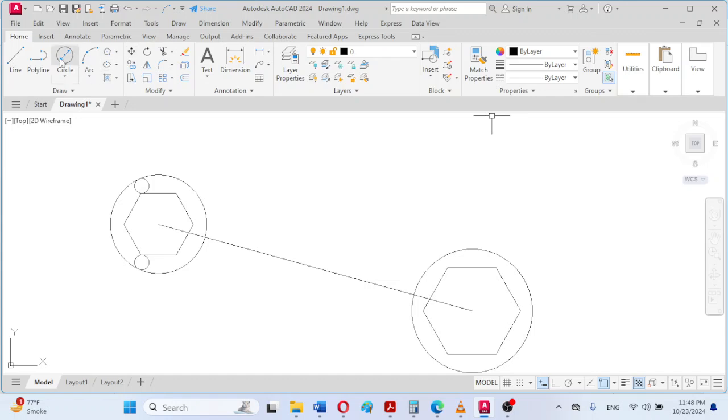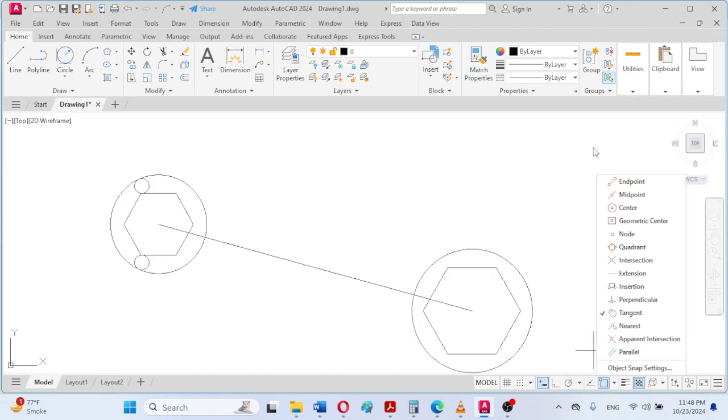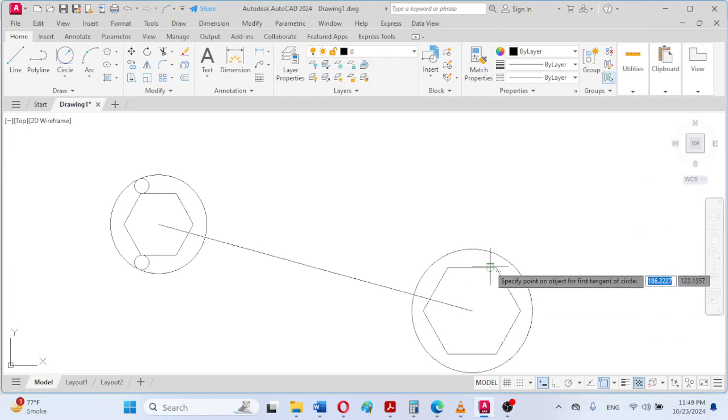After that we will start the tangent radius command, and then we will activate the tangent O snap. If it is not active, we will activate it from here. We check it, it is already active, and then we click at the approximate locations here and here, and type its radius to be 3 units. In this way this TTR circle, tangent radius circle, has been drawn.